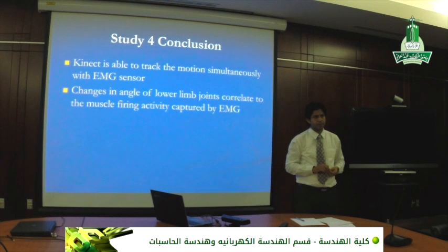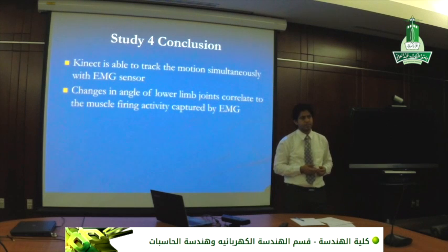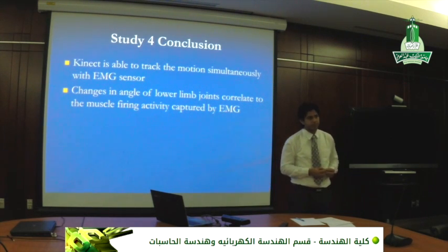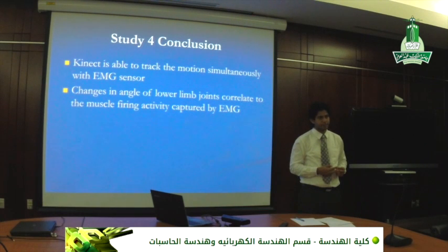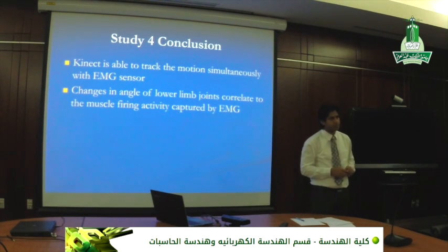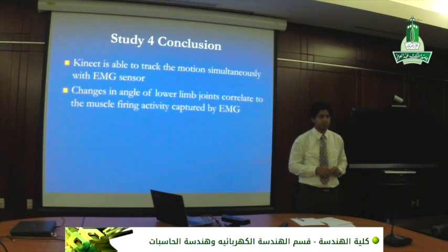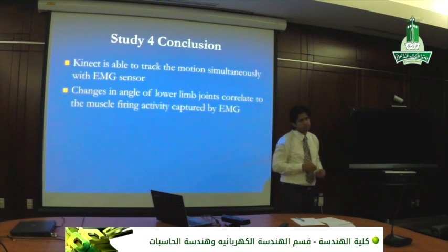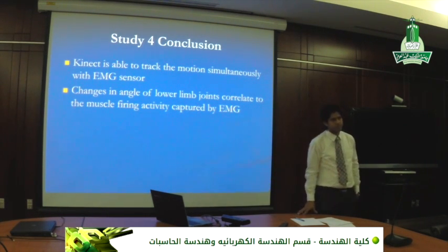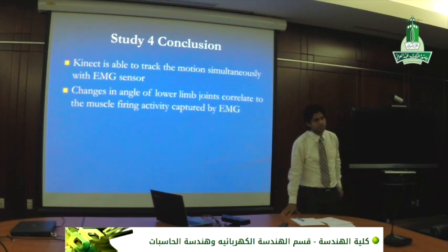Simply put, you have the motion, you take the first derivative and you get the velocity, and you take another derivative and you get the acceleration. If one of the sensors is an accelerometer, it gives the acceleration. So if you want the absolute position or the real motion, you have to integrate it two times. And once you have integrated it two times, you have to take care of the zero bias, the initial conditions, and many more things. Otherwise, the results cannot be correct.